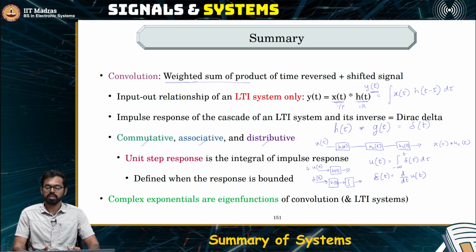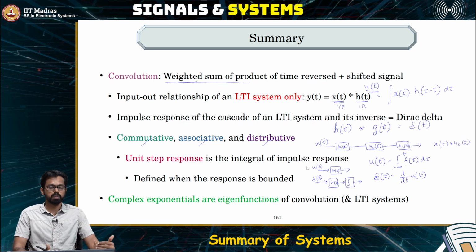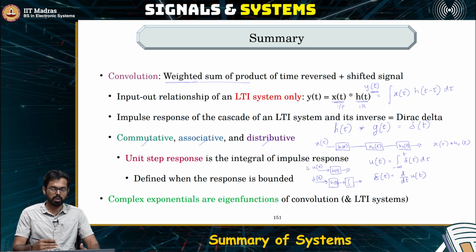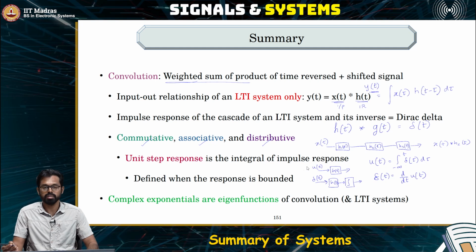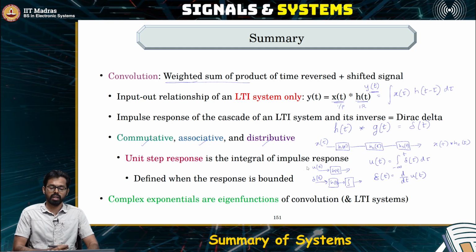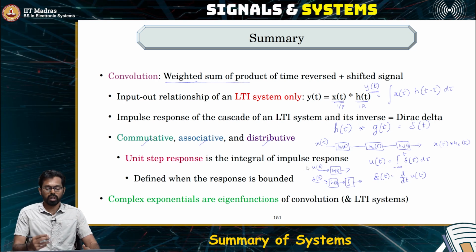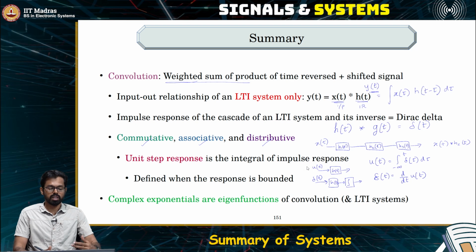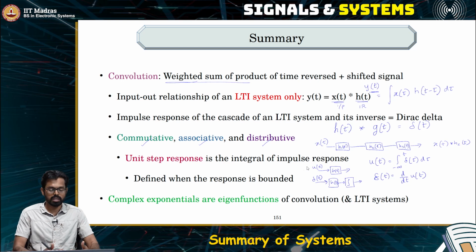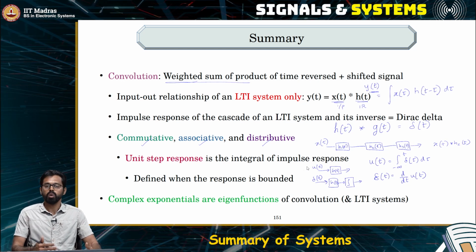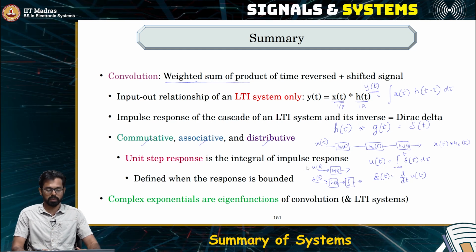That is an interesting observation, because whenever a system is unstable, it means that there exists an input for which the system grows in an unbounded fashion. So if there exists an input for which the system's output is undefined or is infinity, then you can scale that input by some amount and you will still get an undefined output or infinity. So you have essentially found two signals which will produce the same output, and hence it also becomes non-invertible. So most often it will happen that whenever the system is unstable, it is also not invertible.